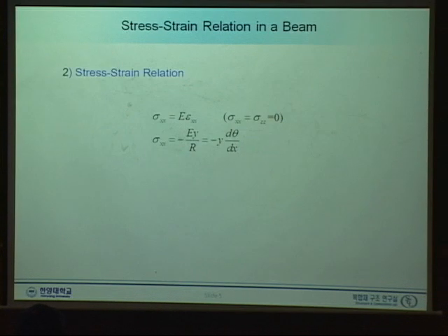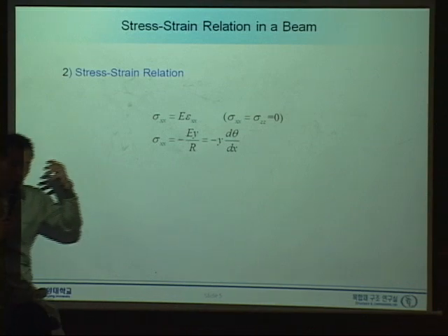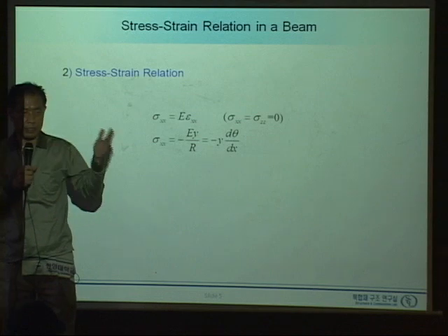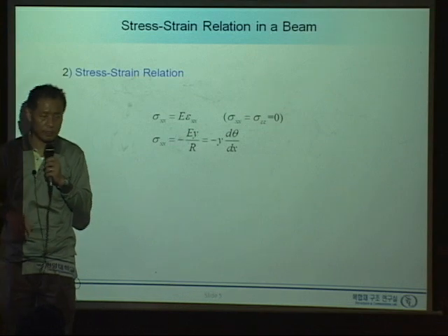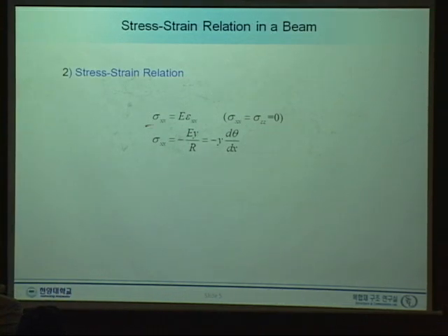So this is the strain, and next, what is the next step? The next step is always deformation, strain, and stress. Now, how to introduce stress? Well, we simply use the stress-strain relations, and since this strain is the axial strain, the material property we need is Young's modulus E. So here, the E is missing, right?